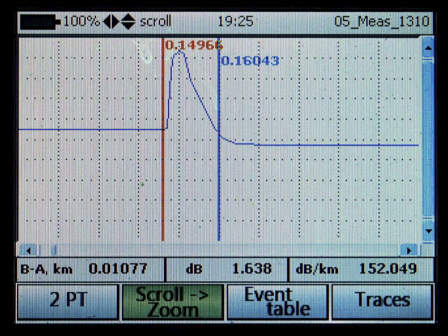When the OTDR chose its own parameters for an auto test, it chose a 25 nanosecond wide test pulse. That's probably not a bad idea for auto test because you don't know if the cable's 1 meter long or 20 kilometers long. But it's certainly not optimal for our 1 kilometer cable. There's a lot of excess energy in that pulse, and that's part of what causes all the ghosts we saw in the trace that the OTDR gave us at first.